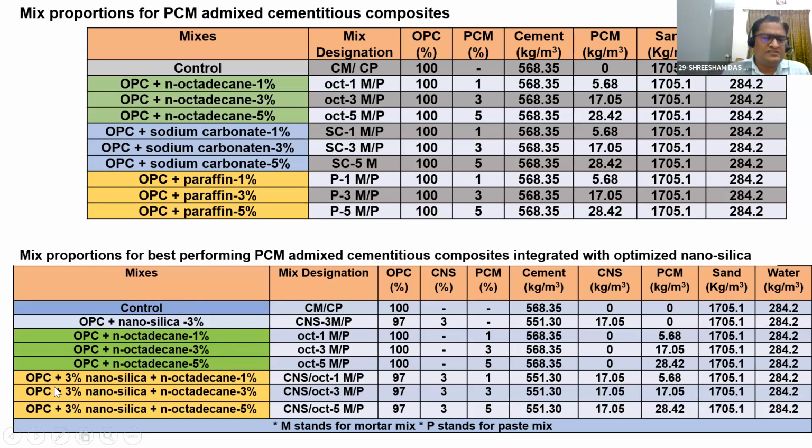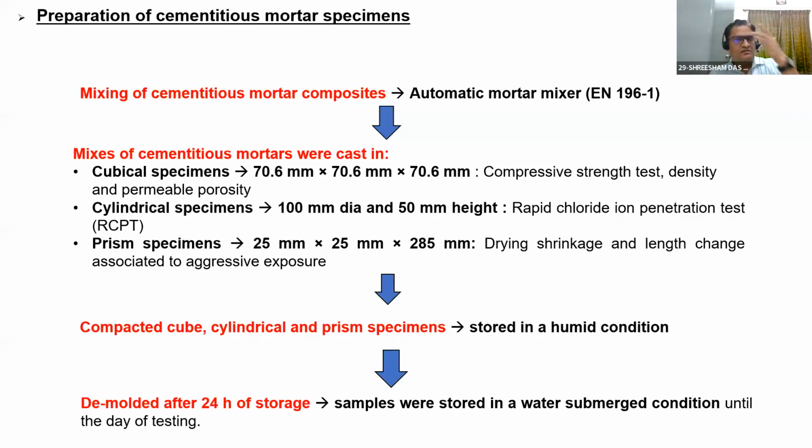For all these three mixes, I have added 3% of nanosilica, as in one of our studies we realized 3% nanosilica gives the optimum mix.